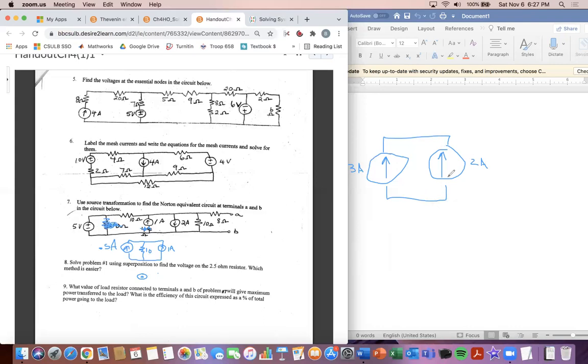It's sort of just accepted, and I know what you mean. This one's going to hit this one. I usually think of a circuit as a loop. It's one thing you have to accept for source transformations, because source transformation is a different method than node voltage or mesh currents. So that's the way it's accepted in source transformation, because you can choose 1 of 3 options. Here we chose source transformation, and that's a rule that you have to add these current sources in parallel, and they have to be in the same reference direction to add. If they're in opposite reference directions, you have to subtract.